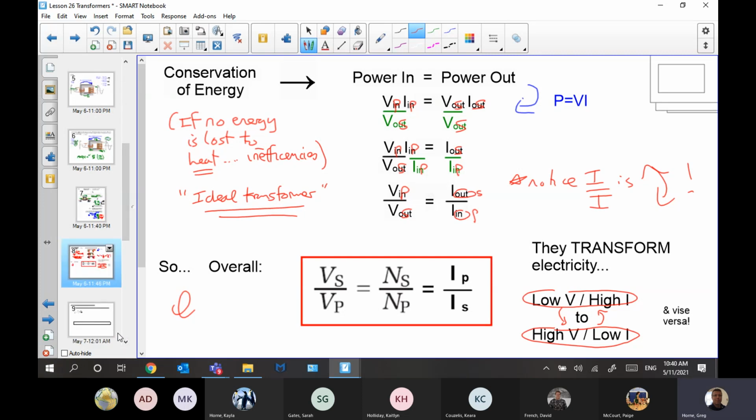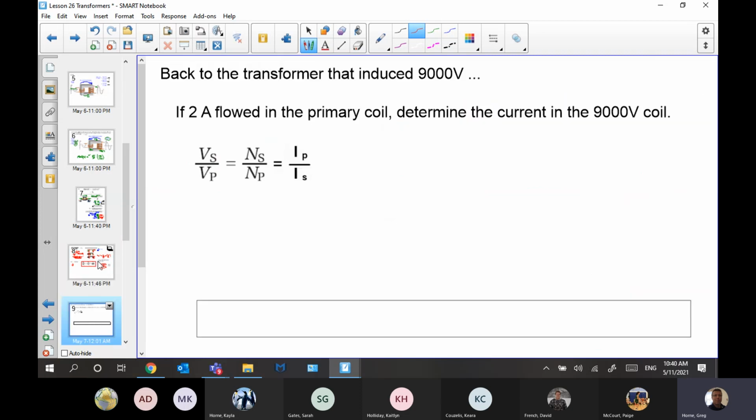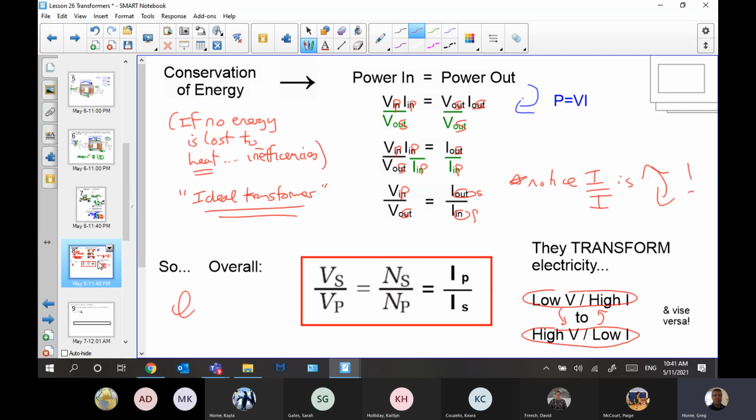So for example, with a device that you're plugging in, like a computer, the motors and the chips and whatnot in computers don't run at 120 volts. They actually run typically at like 12 volts or 18 volts, things like that, just because they function better at those voltages. So you have a transformer in the back of your computer, and it's certainly in the power cable for your laptop, that just transforms the voltage of high voltage, low current, actually, in the case of your house, right, to being lower voltage but higher current in your computer, the thing you're plugging in.